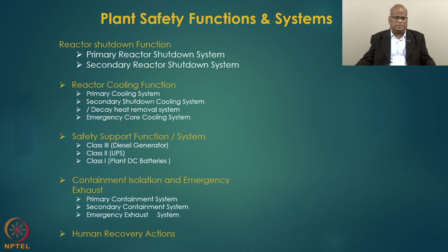And now once we do that, that is, we have a list of initiating events, then we start doing safety system modeling. Now we have got initiating events and their frequency, and now we have to identify the safety systems, which is not a big deal, because from the plant document it will be coming. But then we have to understand their processes, how they operate, what interlocks and controls are available. So let's say reactor shutdown system, there are 2 systems. I told you about redundancy in the system itself, and then redundant systems. So primary shutdown system failure, secondary shutdown system, they are the 2 independent systems for reactor shutdown. Okay.